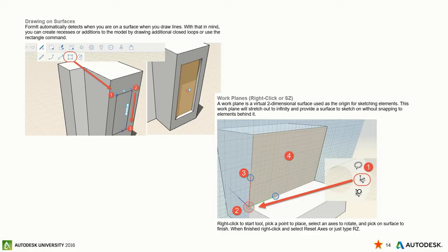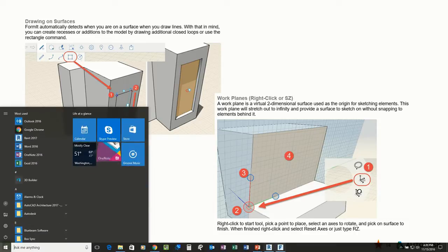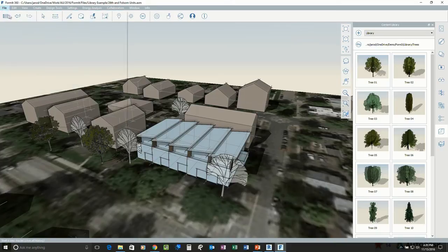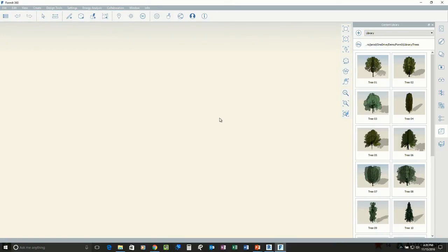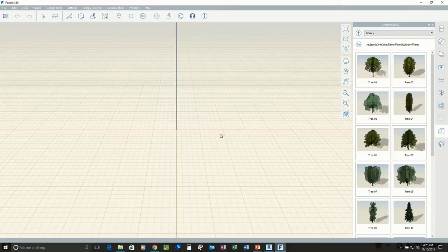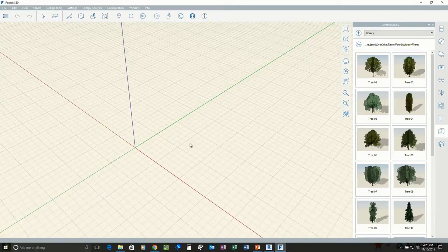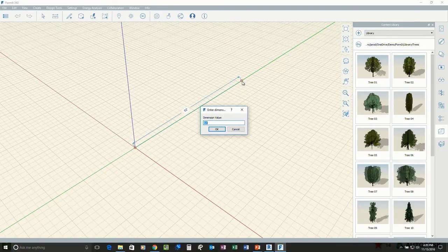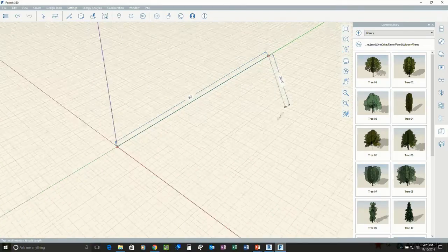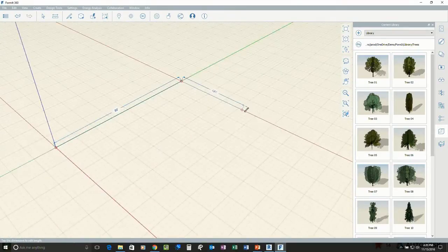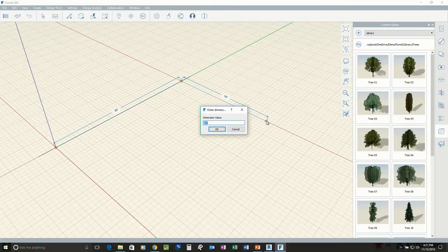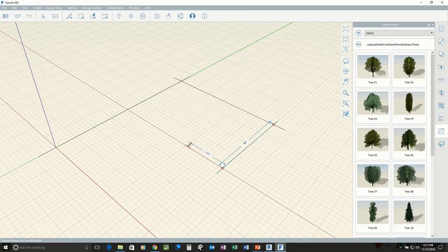All right, so I blurted all that out. All I'm going to do at this point, and I'll do it real quick since a lot of you worked with FormIt, but I just wanted to make sure that I went through, and I'm just doing some shortcut keys just to turn on the grids and stuff. The line command is just L and hit enter. Again, if I want to do precision, it's basically the tab key. I just hit the tab key, type in whatever distance I want to do, hit enter. Obviously, you can zoom and pan around if your mouse is acting normally. So my Dell mouse sometimes likes to not think I'm doing that. And so I can just come in, type in, flush out whatever I want to do. Obviously, all of this can be changed at any given time.